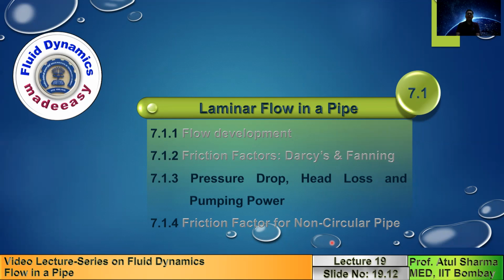This head loss indicates... normally we use a pipe to transfer, let us say, liquid from a smaller height to a larger height. So this gives you an idea of how much loss in the height, due to the viscous resistance, by which we could have transported the fluid. So the pressure drop is converted into a head loss that will be presented in this section.